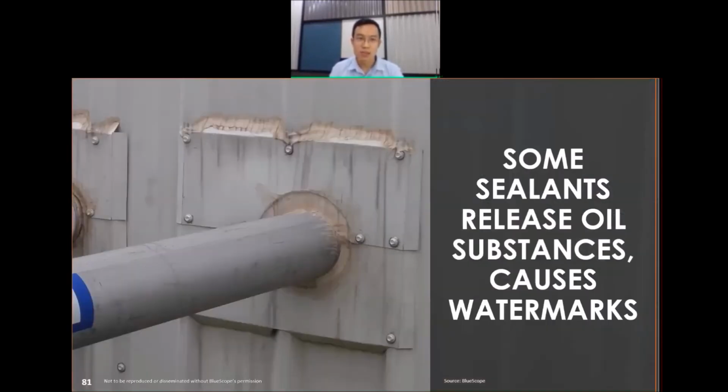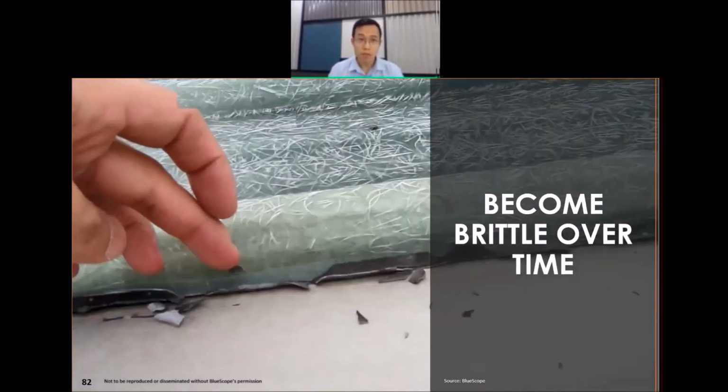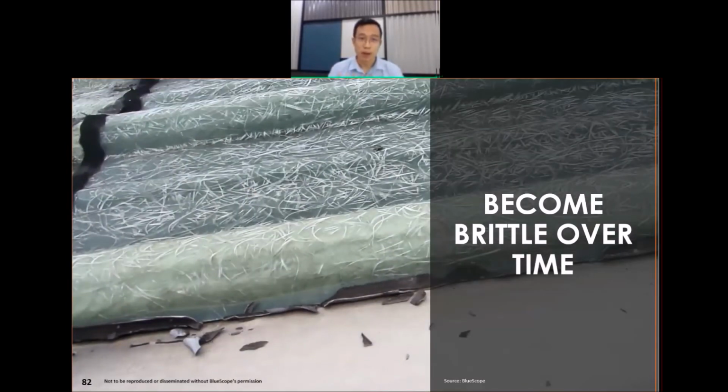But sometimes sealant itself can actually release oil substances upon breaking down. Some sealants might not release such watermarks, right? But some that are not performing might actually cause watermarks like this. So it will be hideous for you to use that kind of sealant. Okay. Another thing is that sealant itself can be brittle over time. So you might not expect it to permanently seal the gaps for 20 years, 30 years' time.